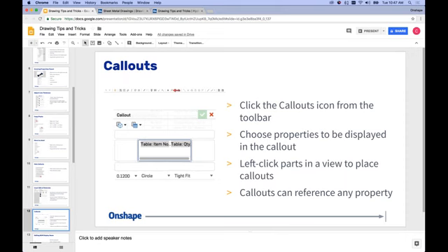Now, I should point out there's no way to just delete a row from the bill of materials by itself. But if I deleted parts from the assembly, that would cause the item numbers to shift, absolutely. It does not remain static. I hope that makes sense. You could reorder it afterwards, but if I deleted a bunch of parts and removed an item number that's no longer in existence, it would shift everything up, I suspect. Right?